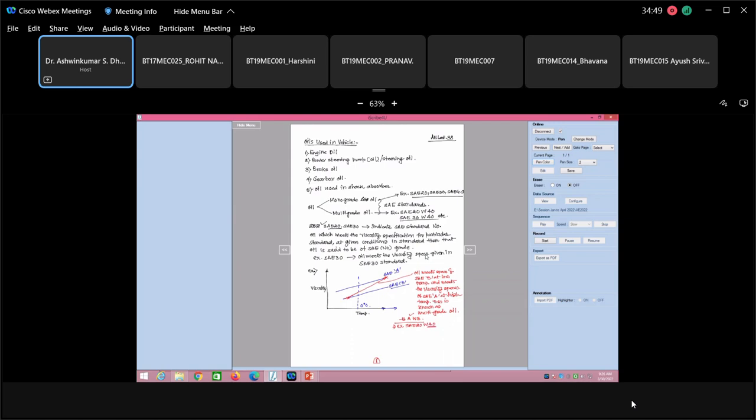So the oil is meeting the specification of SAE 20 at the high temperature, whereas it meets the specification of SAE 40 at low temperature. So that is why you have SAE 20W40, and this is the reason why the automotive industry specifies only multi-grade oil.